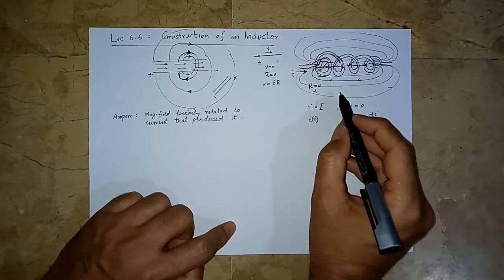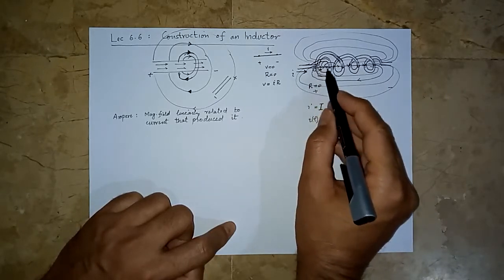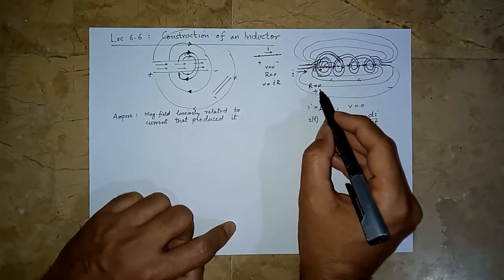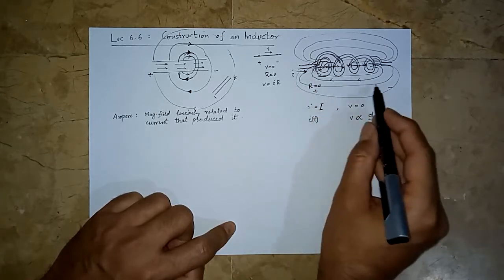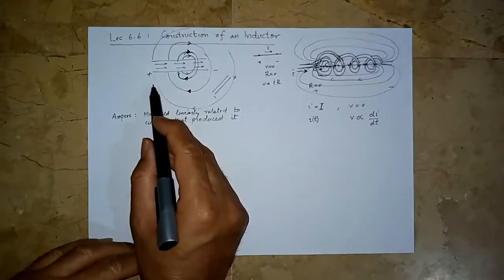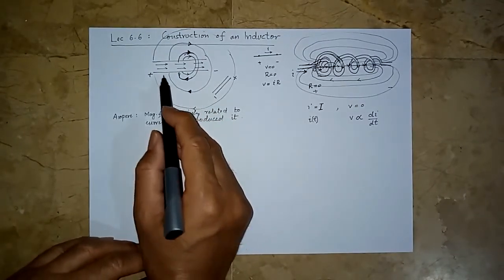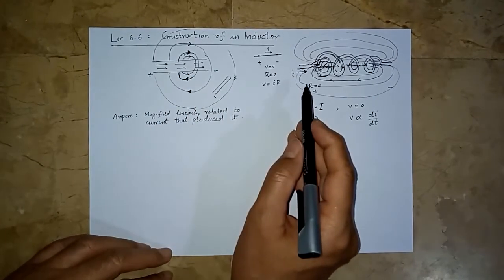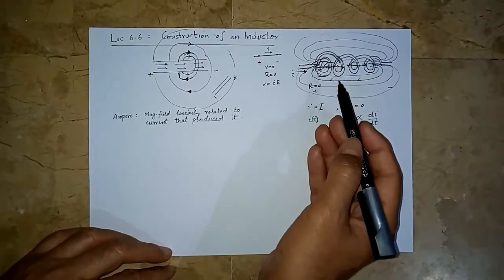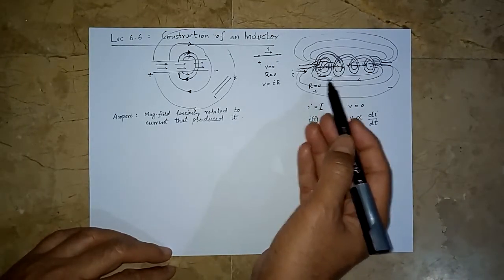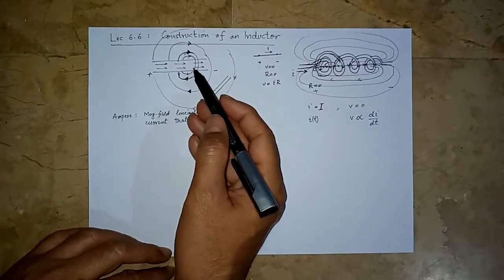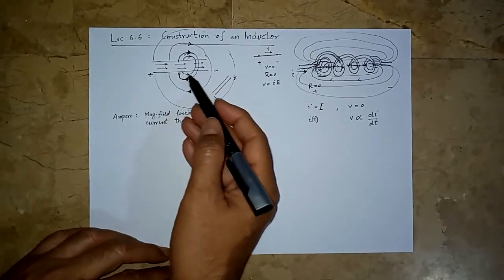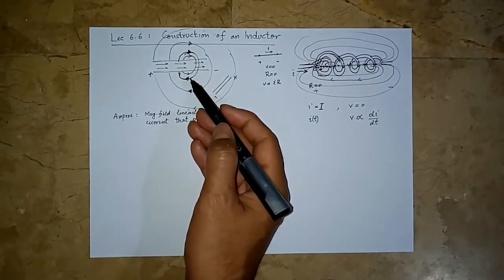And this is something interesting because although it is still a wire with zero resistance, we have now voltage across it. So a straight wire is not going to have voltage across it because this inductance aspect, or this experience, we can say, does not happen here for the case of a straight wire.